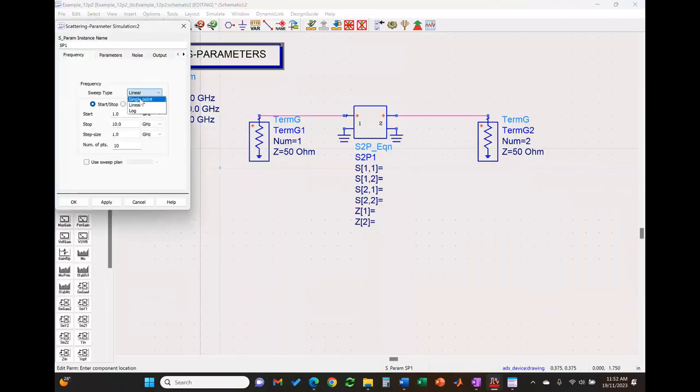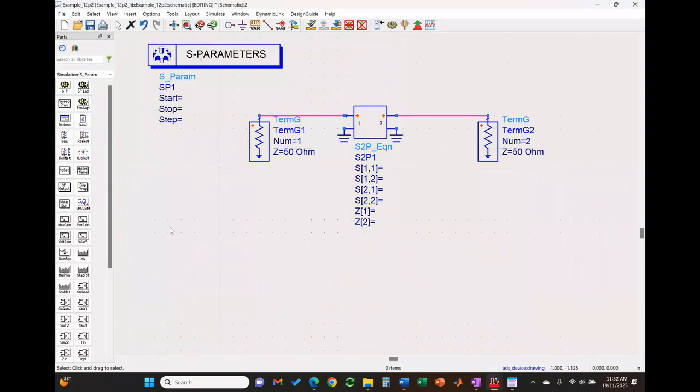Now, again, in this example, the simulation is done at a single frequency, a single point, which is 1.9. Let me add this here. Now, the next step, I still need to add my S parameters according to the information which is given. So the first one, again, is 0.869 at an angle of minus 159. In rectangular form, this is minus 0.81 minus J times 0.31.